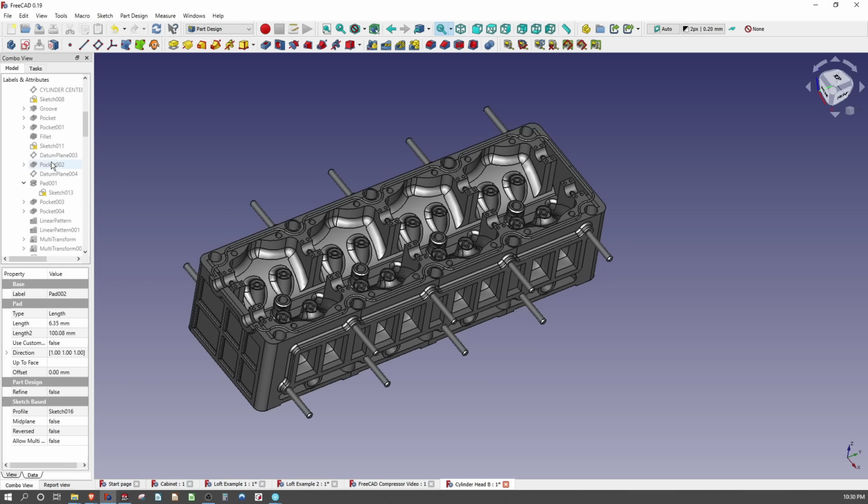So in this case, we've run into a topology naming error, but in other cases when I've had to rebuild very long trees in FreeCAD, sometimes it takes a little while. So keep that in mind. You can run into topology naming errors on occasion, not all the time, and you also can face kind of long rebuild times. So Alibre, in this case, would be very friendly towards long history trees and good rebuilds, due to topology naming and just working relatively fast for things that are heavy.